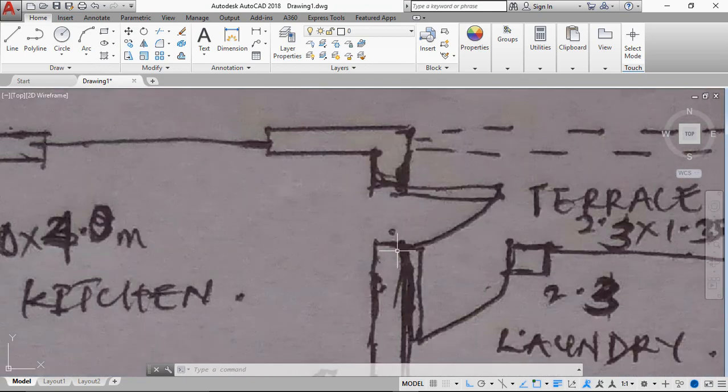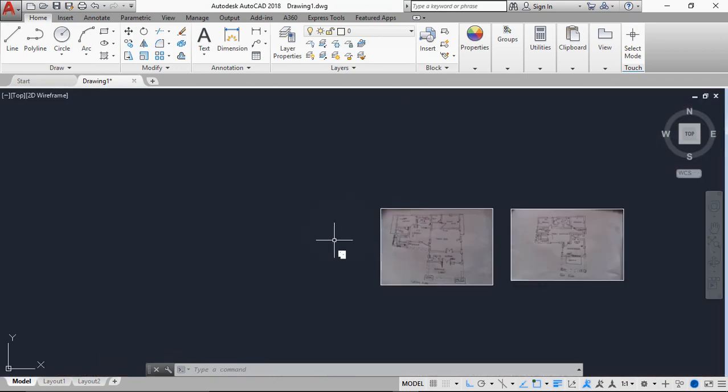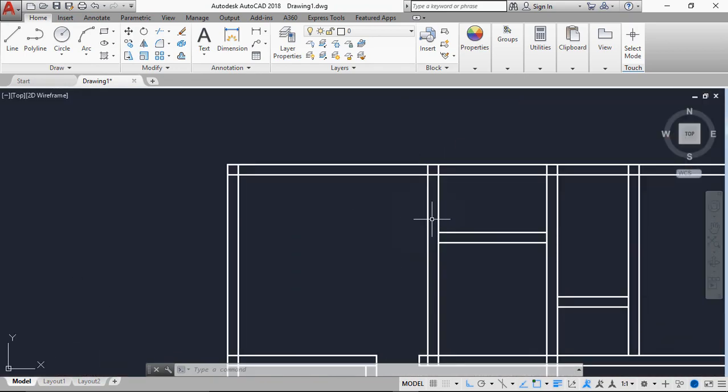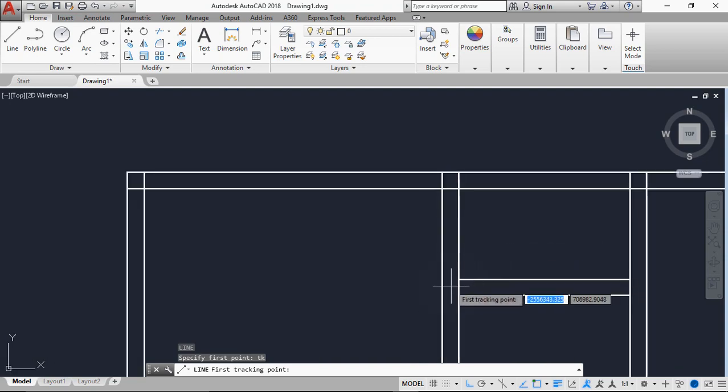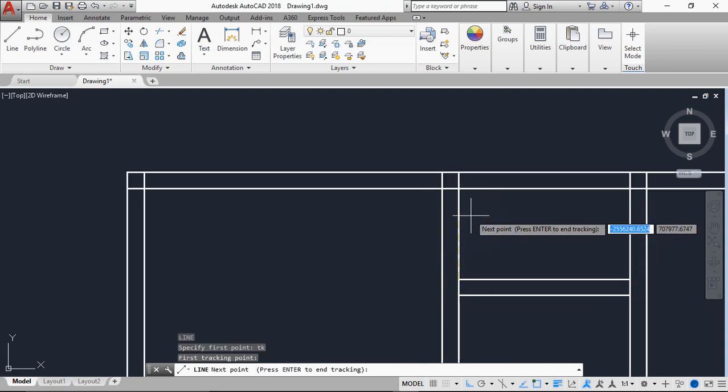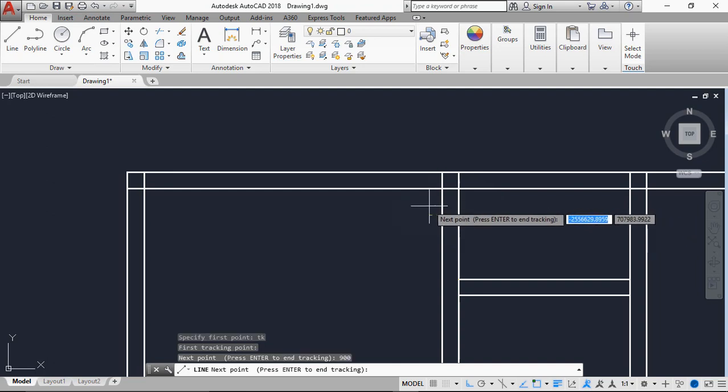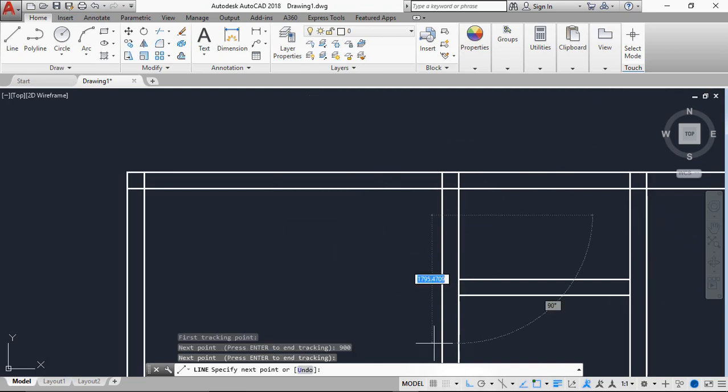So next one is creating one here again, which will also be 900. So I'll start from this point again and create 900. Use the same approach. Click on line, type in TK, hit enter, select this point here and move up a bit and type 900, hit enter again, and make sure your auto is turned on to make sure that the line is perfectly at 90 degree or 180 degree, which one you have on your screen, and click to draw that line.